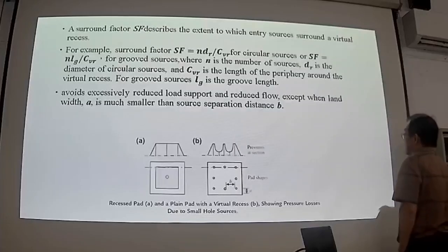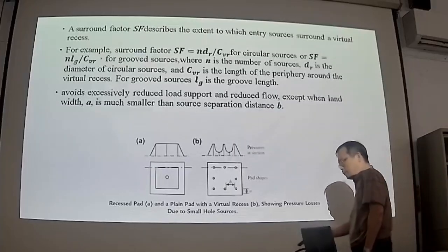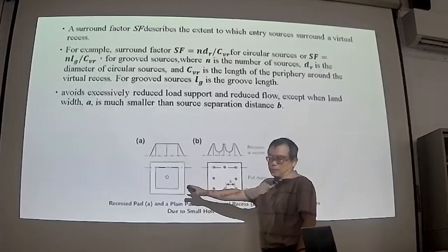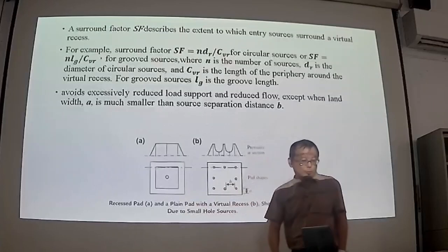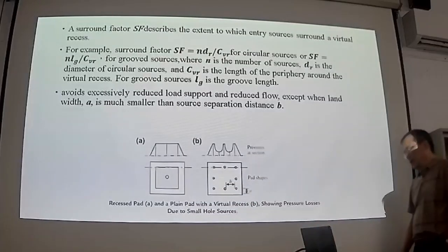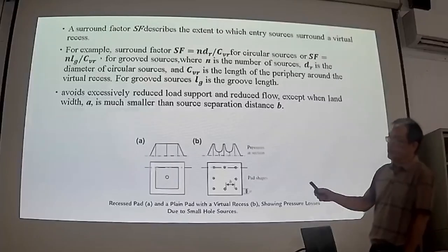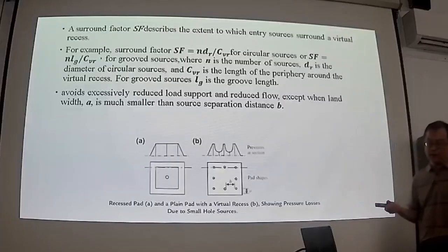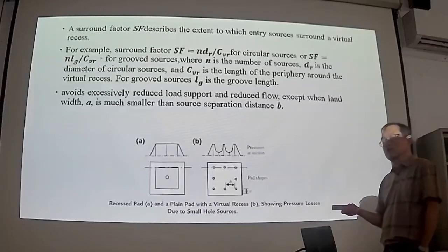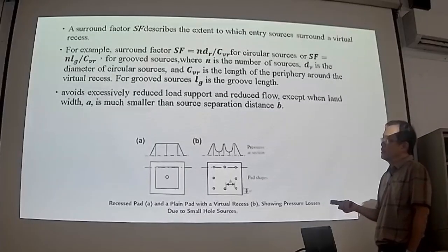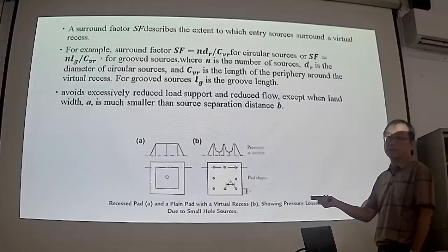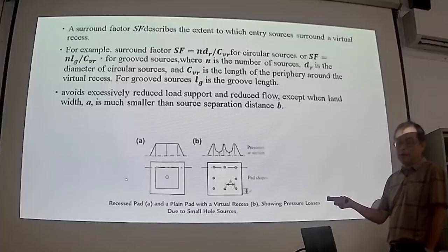Okay? So for the hydrostatic bearing, because usually we use lubricant as the working fluid, during the normal operation status the supply pressure is lower than 60 bar, so it's incompressible. So we can design the recess for the hydrostatic bearing.